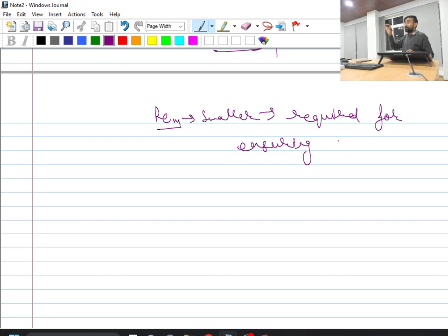Because viscosity of the model has to be low, but if in your model you are not using that hypothetical fluid and you are using your generic fluid, water only, for the model also, then ultimately your viscosity condition is not satisfied. Whatever Reynolds number you get for the model, because you are using high viscosity fluid now, will be smaller in comparison to that required for ensuring dynamic similarity. Is this point clear?